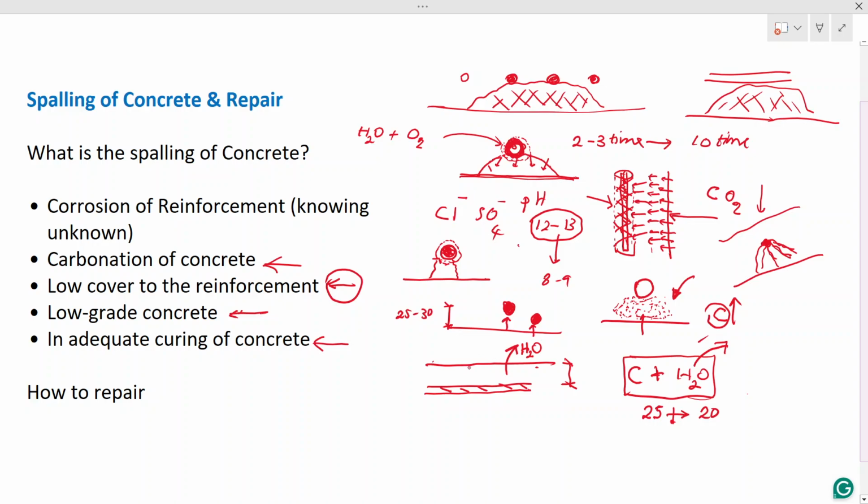The second thing we are going to discuss is that with a high rate of evaporation of the concrete, shrinkage cracks will appear in the concrete. Faster evaporation will create the shrinkage. With the water evaporation, the volume will be reduced, then cracks will form. These cracks could penetrate even up to the reinforcement like this.